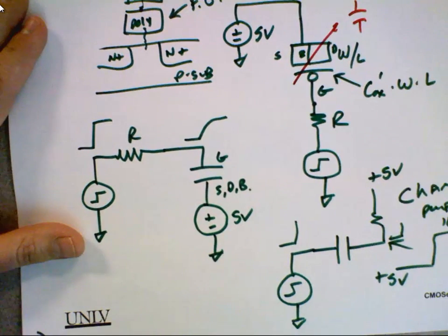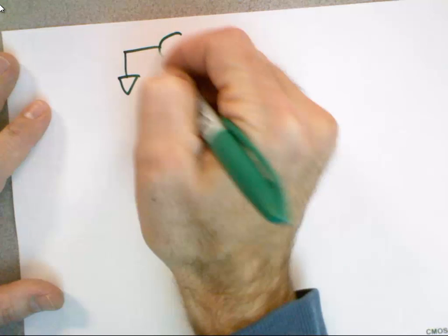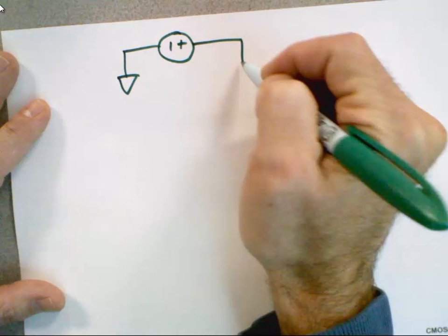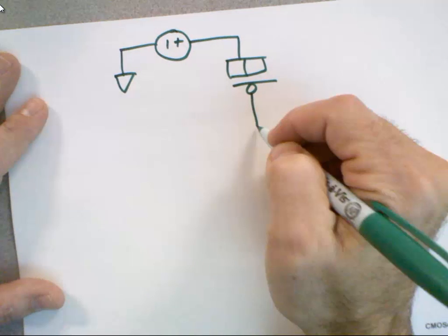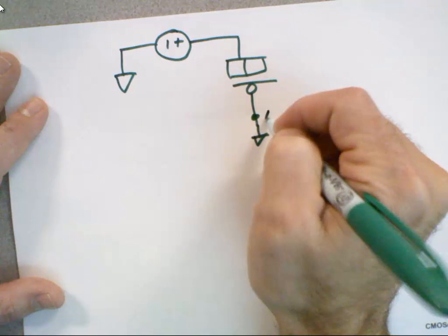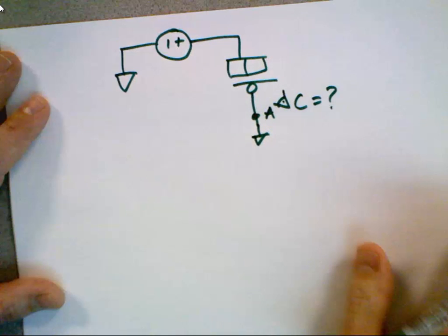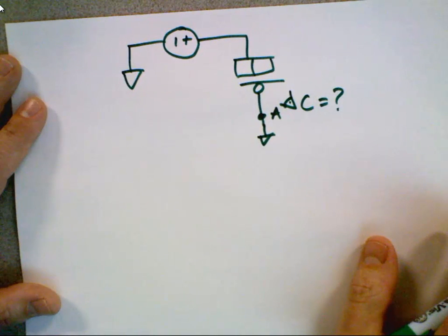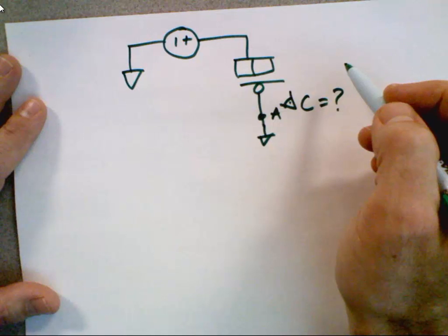One other thing I want to talk about before we move on to reviewing strong inversion for your simulations. When you are doing your sims, let's just do the PMOS, since that's the one we were just talking about. I don't remember the exact homework problem, but it was like, this is A, and that's my eyeball looking up: what's the capacitance I see looking up? You calculate it, oh, it's easy, Cox prime times L times W, but you want to verify it. How do you verify it with a sim?